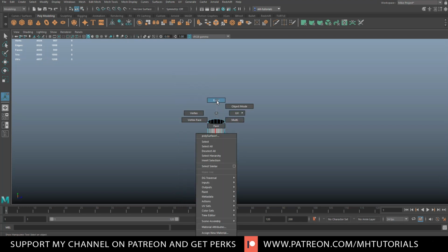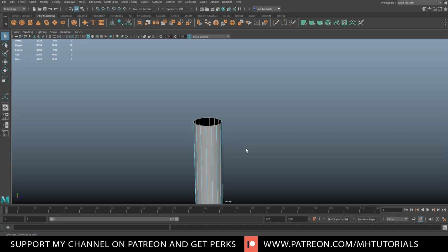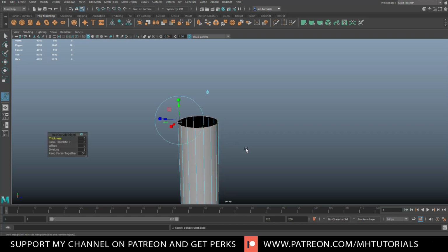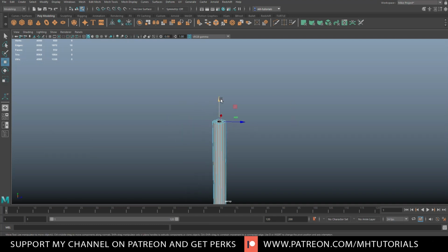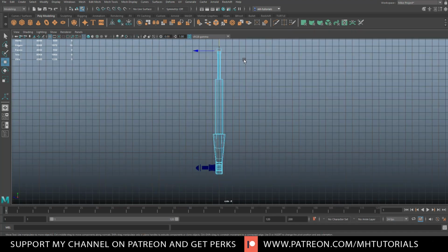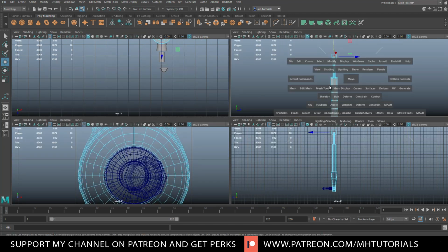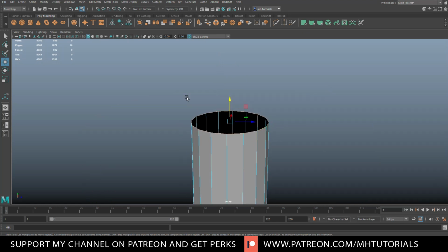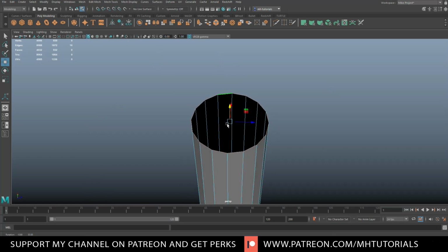So we'll go in here, we'll get an edge, we'll double click on that, Control E to extrude, R to scale in again to about there, I would say, and then G to repeat, W to push up. And let's look at the overall proportions again. And that would be about right, maybe even a bit less, like so, all right? Okay. After frame, then what we're going to do next is we're going to go and close that up.